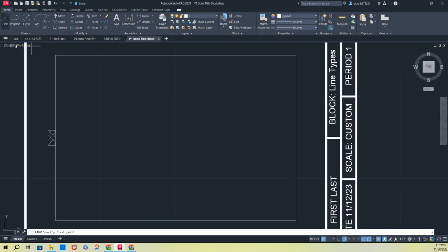There we go. I'm going to draw a center line. This is going to be just a construction line. It's going to be 0.5 inches. Hit the escape key. Now I'm going to offset this line 3/4 of an inch in either direction. Click 1, 2, 3, offset it, type in 3/4, enter. Click here, offset it downward, 3/4, enter. Hit the escape key, select and delete this middle line, and then click the line tool and close this off. Okay, next one.